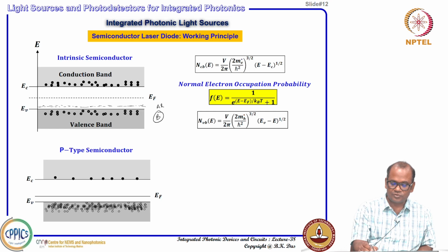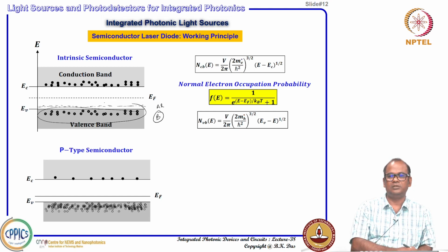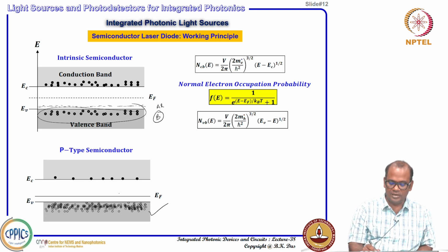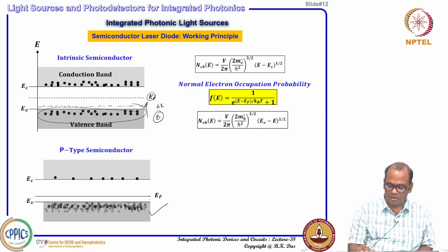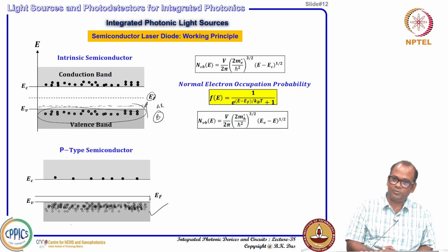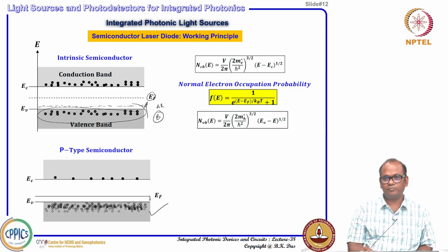Once it is created here, a lot of electrons can get a little bit of thermal energy and occupy these states. So, you get a lot of holes created in the valence band, meaning electrons are going a little bit up. When electrons are going a little bit up, the occupation probability, where you are supposed to get half occupation probability, that Fermi energy level will pull downward. So, in a p type semiconductor you can have a lot of holes that can be conductive, and the valence band itself, because of the holes, starts conducting, okay.